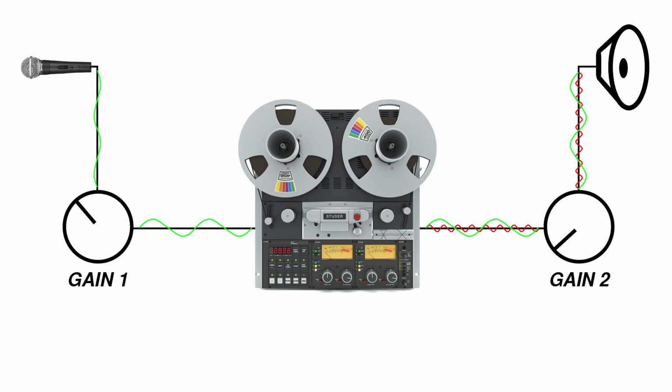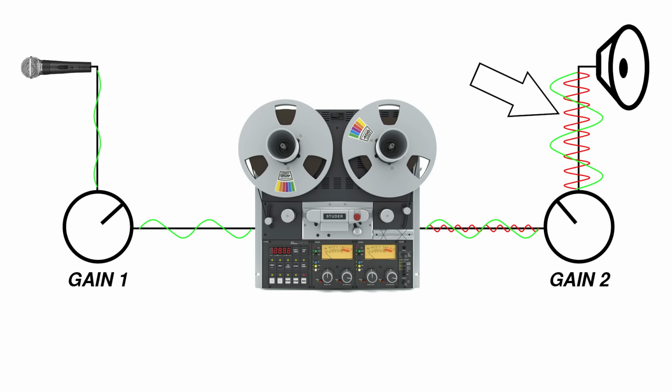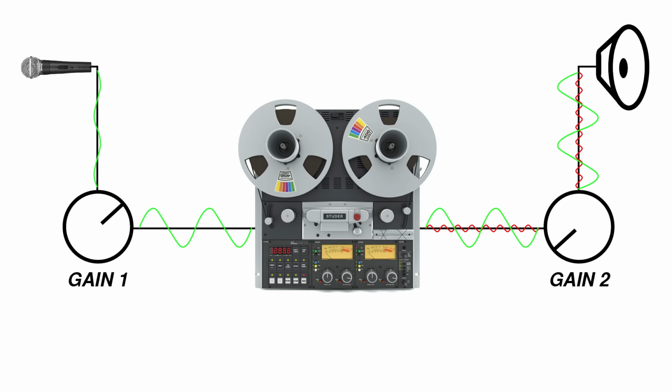Plus, once your voice is recorded, you'll need to turn up the signal to bring it to a usable level. And when you boost the signal, you'll also be boosting the noise. If a strong signal is sent to the tape from the beginning, the signal-to-noise ratio will be much greater.